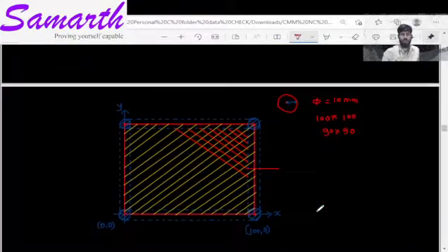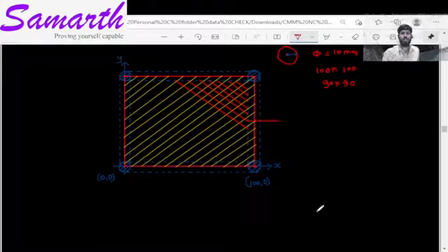This was all about NC programming. Now we will see why we were using those compensations. Let us say this is the circular tool and I have given the coordinate 0, 0. If you cut in this manner, the cut portion we finally get will be 90 by 90 instead of 100 by 100, because this cutter itself has some diameter, which is, let us say, 10 mm.